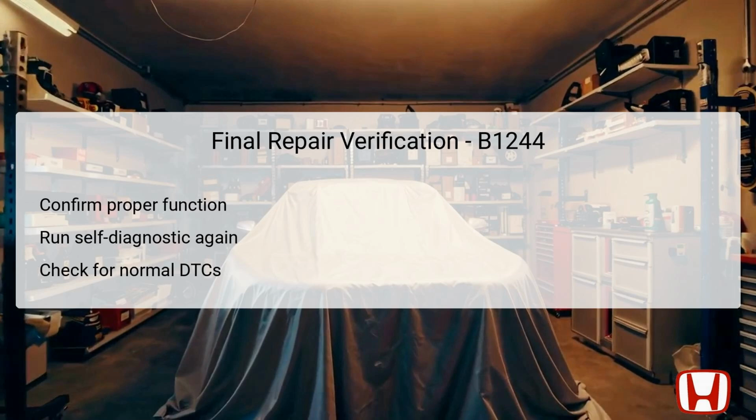After completing repairs associated with DTC B1244, it is vital to conduct a verification to confirm that all components are functioning properly. This should include running the self-diagnostic function again to ensure that no new error codes appear and that the previous DTC B1244 does not return. It helps to ensure that the rear air mix control motor and all associated circuits are now operational.